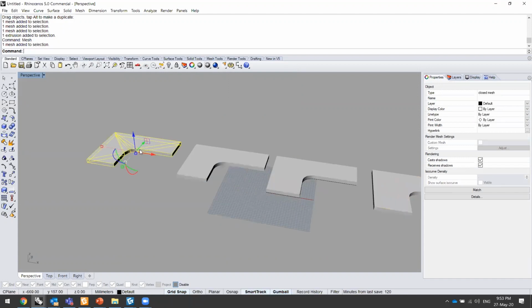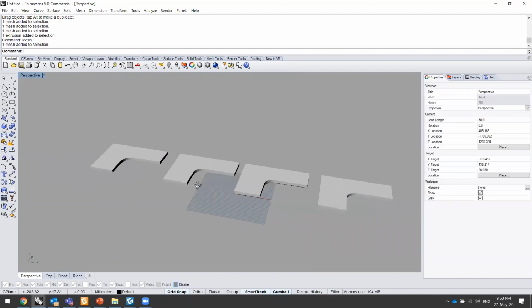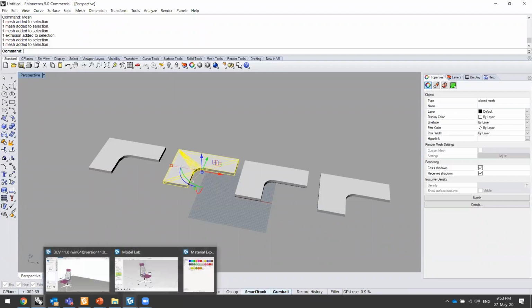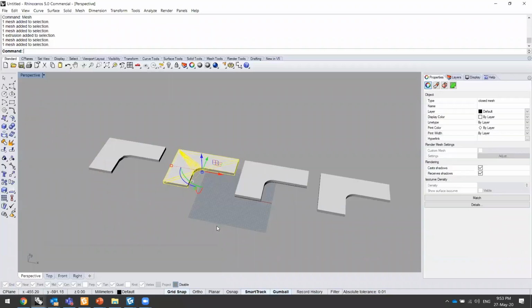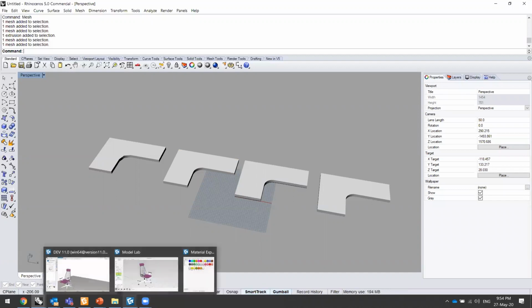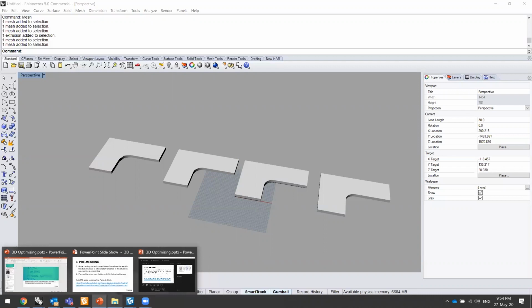The advantage of pre-meshing might not just be this. We have way more we can control much better. We can say for this part, it's a simple part, I can reduce it to where it looks optimum, and this I'm just going to allocate much more triangles to it. When I bring everything to Model Lab, it looks good already. There isn't much I need to do in terms of balancing the polygons in Model Lab. So your CAD environment might be better for you instead of in Model Lab. Okay, so I hope that answers your questions. Dave?